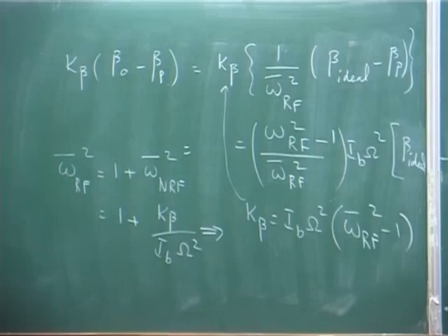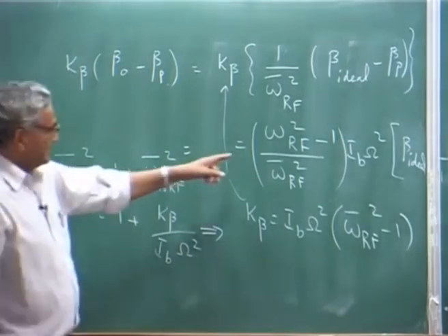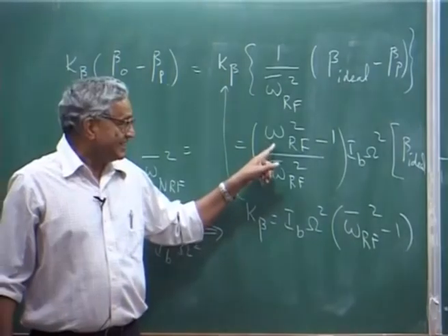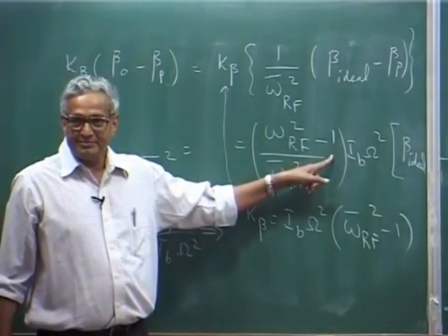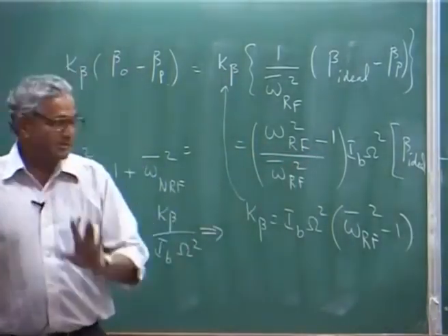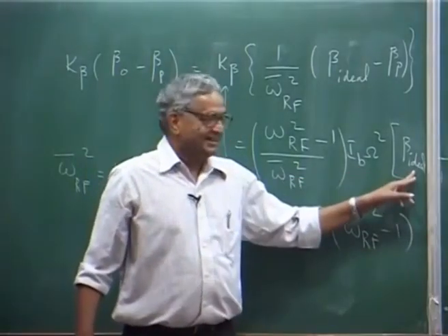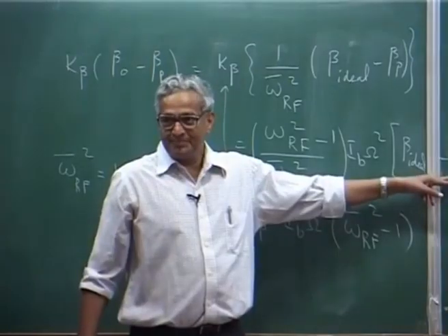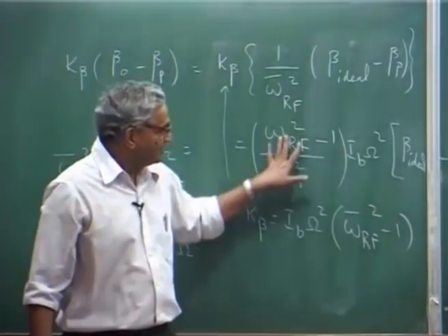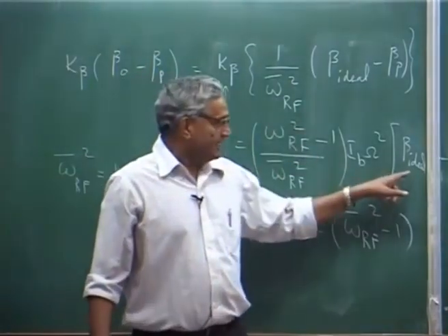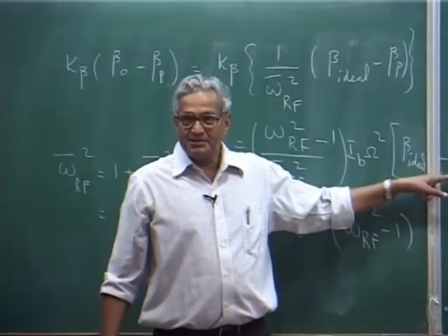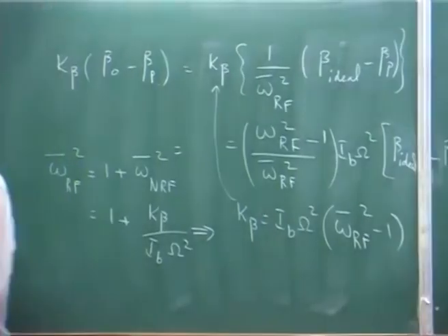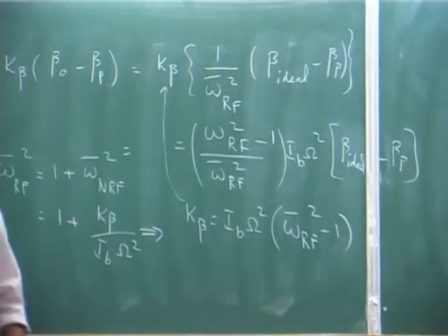Okay. Whereas, the moment you have a rotating flap frequency greater than 1, then you get a hub moment, but beta ideal is not equal to beta p. So, now you may have any frequency, but if beta ideal is equal to beta p, then you will not get any root moment. Okay. But it is not that you do not want to get any root moment.